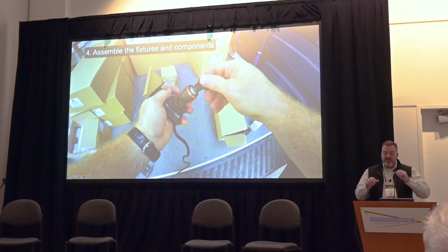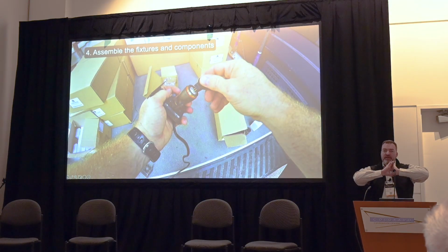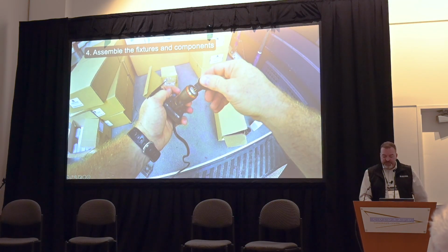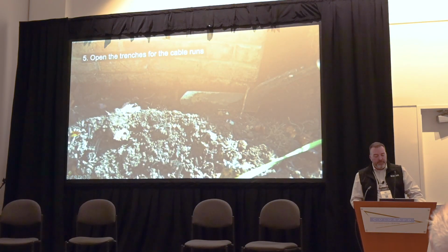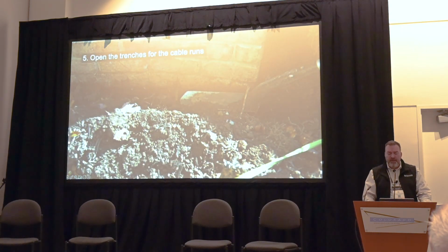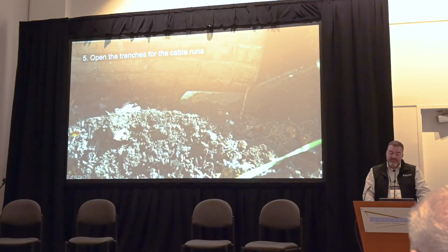But have your tech put those together, and sometimes your lead tech will get done with the transformer first, have them come back and help get the fixtures out. And then once the fixtures are laid out, your power center is all done, now you guys start opening trenches and we start pulling all together. I'll talk a little bit about where we place trenches. But now you guys want to start opening those trenches, and this is going to be the part that everybody hates. Nobody likes to dig, but yeah, it's not bad.